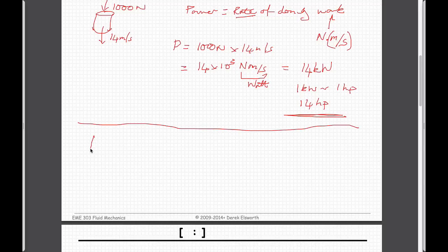It's probably a two-liner, right? There's this guy lying down, pedaling somehow. He has a velocity ahead of him, hitting his head, and in doing so builds up a pressure. Call this point 1, call this point 2. The elevations are the same, so we don't care about that. The pressure at point 1 is atmospheric, so we don't care about that. The velocity at point 2 is 0 because it's a stagnation point. So the only components left are that the pressure at point 2 divided by the unit weight of air has to equal the velocity at 1 squared over 2g.